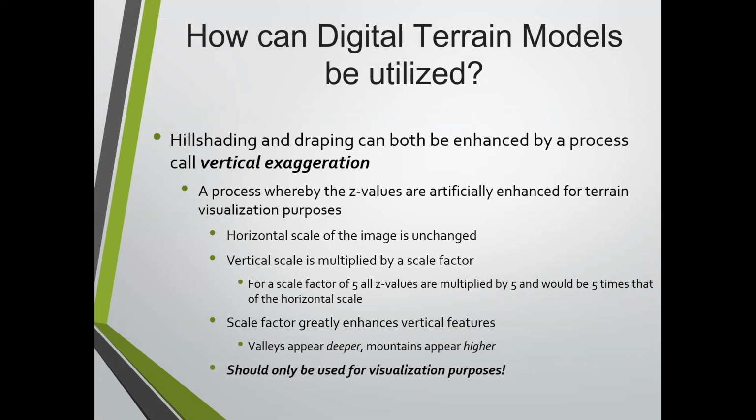What that does is allow you to get values such that your valleys appear deeper and mountains appear higher. And of course, this is only used for visualization purposes. But keep in mind, that's all it is anyway, because in software like Civil 3D, you're actually not altering the 3D terrain model at all. You're just altering the visualization of it.